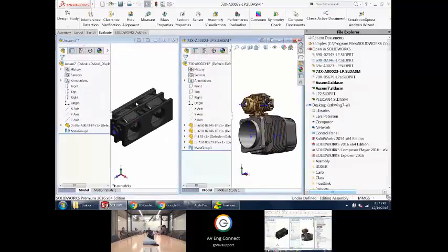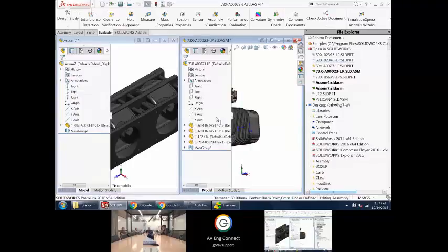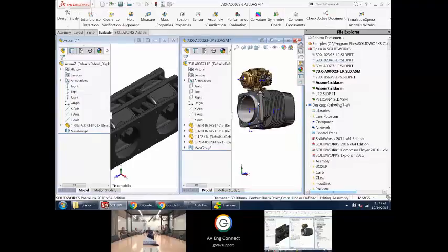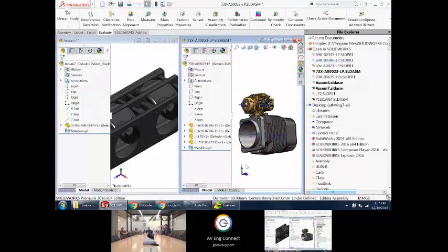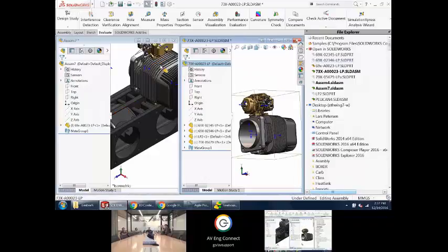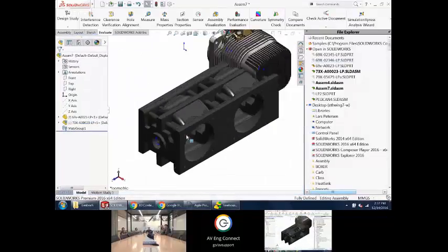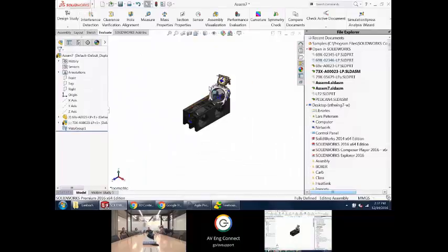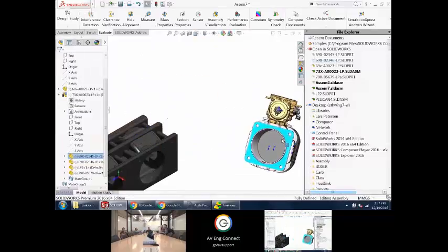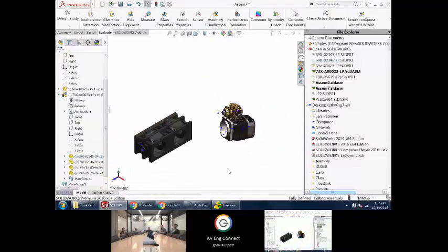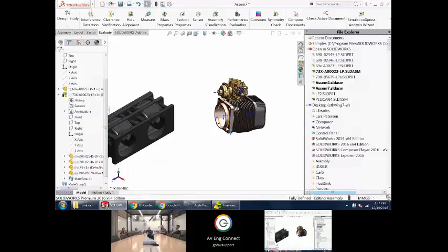Unfortunately, that trick that I showed you where you can grab an edge and Ctrl-drag and drop does not work at the assembly level. So you need to drag and drop the assembly in there first, and then you just need to do the hotkey, the Alt key. It'll still work. It just won't work that window-to-window choice. So close. Though there is a way.